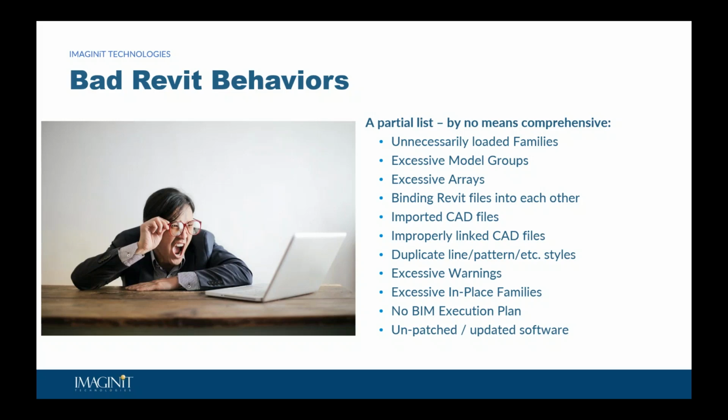Most people know by now that Revit and CAD data, you don't want them to come together. But we also know that it's inevitable. We need to bring in a Civil 3D background. We've got some sort of standard detail we want to bring in, or something from a non-Revit partner on the project. It has to happen, but was it linked? If it was linked in, was it linked in properly to current level only, if that's what it should have been, versus any other settings?